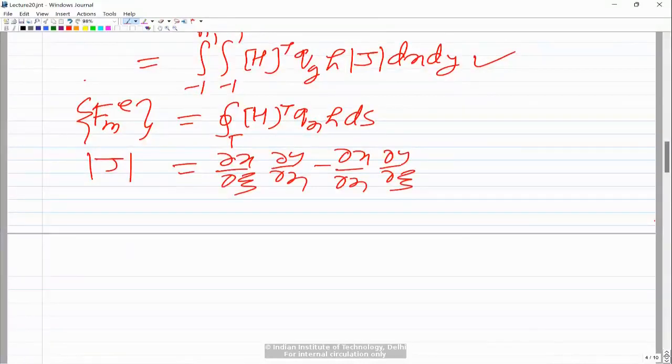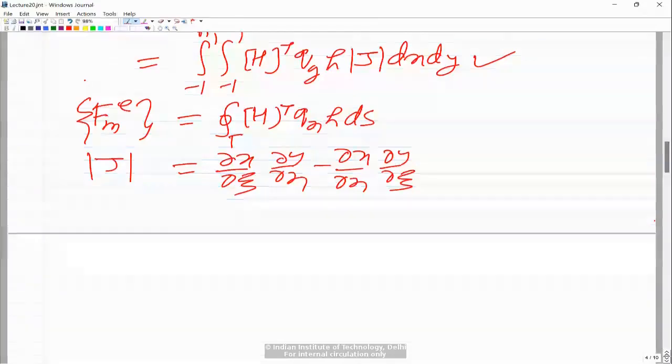So now once we have done this element formulation, the other steps are: discretizing the problem, for given xy coordinates you have to evaluate the element level conductance matrix, external load vector, internal load vector, and then you have to assemble all the elements, impose the boundary condition, and solve the problem. So that part really remains the same.